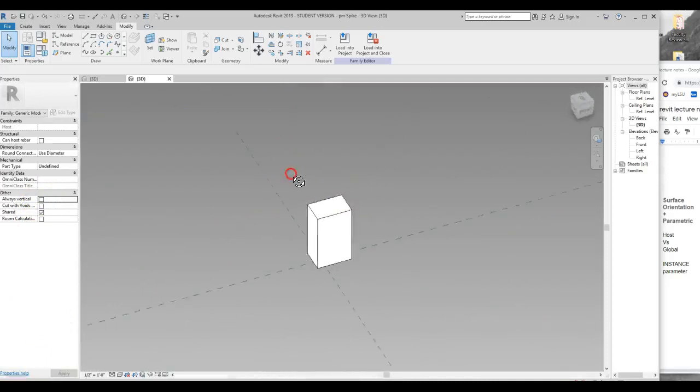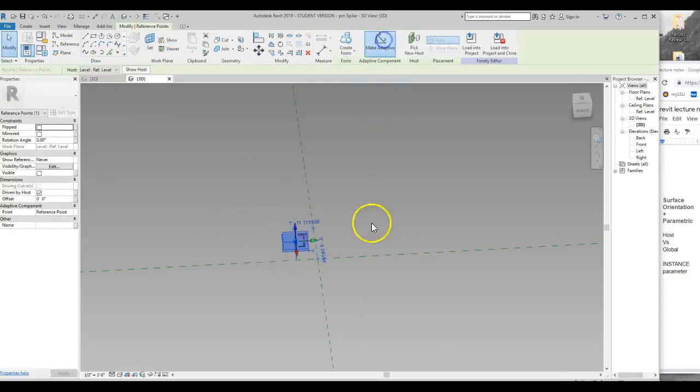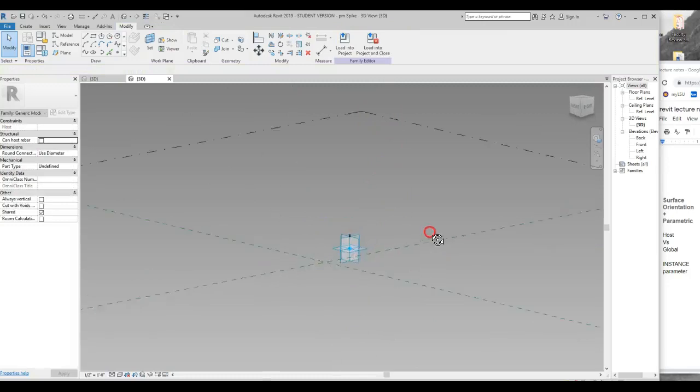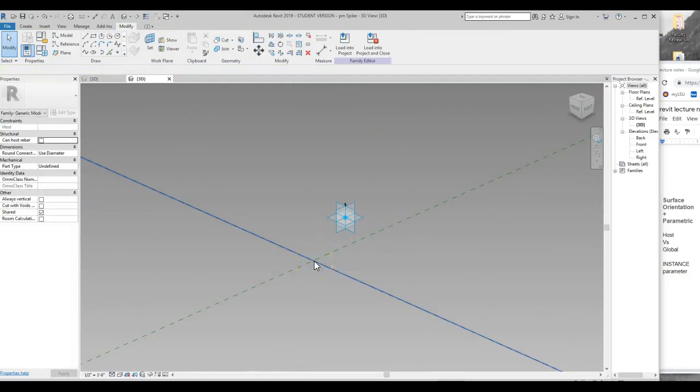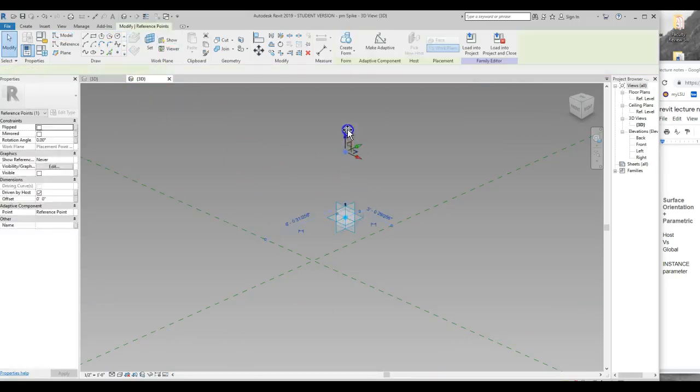And we're going to look at doing a few more complex things. So with the other generic model adaptive stuff we've done, I'm going to delete this. We've usually started by placing a point and telling it be adaptive, right? Be a placement point. So this makes a placement point. When you don't put anything in here, the 0, 0, 0 is the placement point. That's why that box was coming in where it was. So for this one, we're going to start with this, and I'm going to, again, set a point, SW, on that surface right there. Escape, I can grab that point, shift it up.